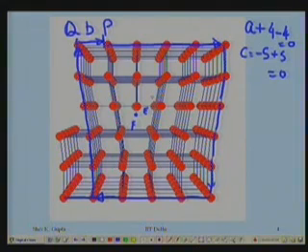So whether I take the direction of the dislocation line E to F or F to E, it is arbitrary and left to the user. Dislocation is a line, nobody has shown it as a vector in the crystal. Direction, once you give to it, it becomes a vector. That's called the dislocation line vector. So let's take from F to E.